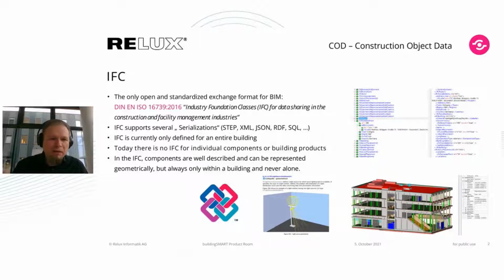This is that you can just handle projects, just handle buildings, complete buildings with the IFC structure we're using today. And this means we can transport quite easily complete buildings with an IFC site, with an IFC floor, and with IFC spaces for the rooms, and with products also. For example, luminaires, this is my industry, coming from the luminaire industry. You can handle luminaires with 48 properties in IFC natively, great stuff, including light distribution. But it's just always in a building. You need to transport a building in order to transport IFC products.